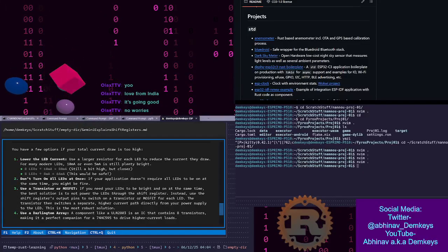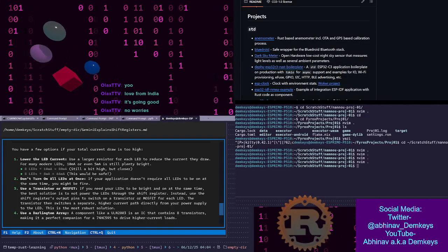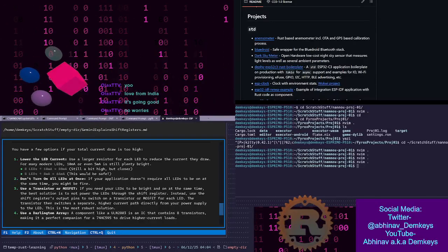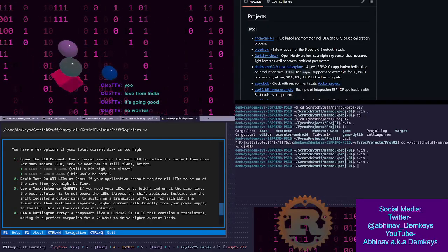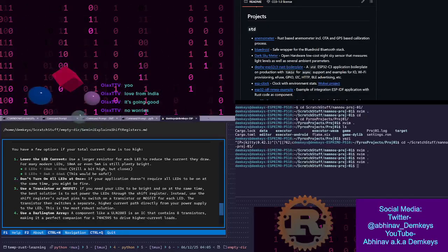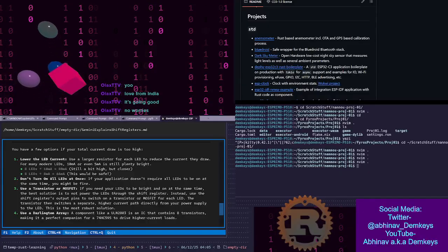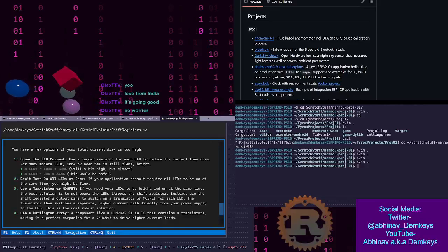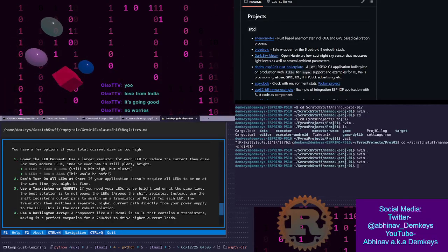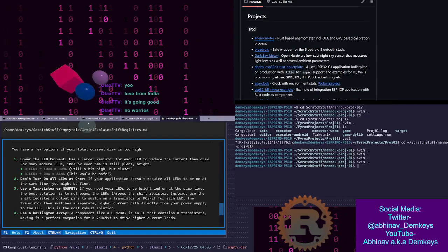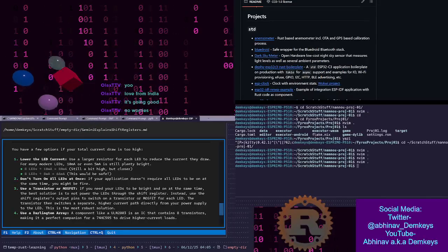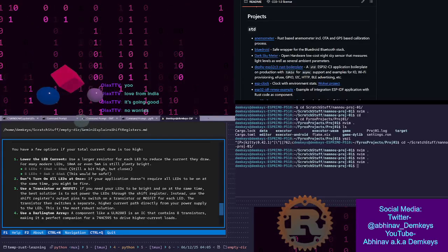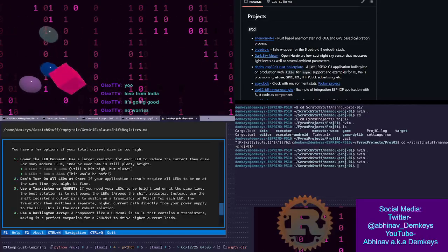Though I feel like I would be able to set this up easily using the components that I have right now. To test this out, I could use a digital pin to send a signal to a transistor, and then have that transistor power an LED going through a resistor. The thing is, when you have an extra circuit involved there, I don't know where you're supposed to be pulling VCC from, and whether it matters where you connect ground to.